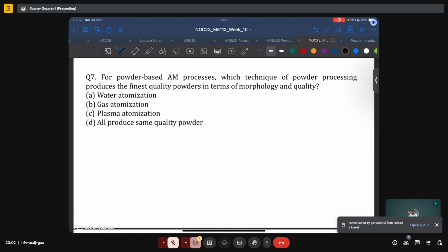Typically, the metal feedstock will be melted and then it will be atomized into small particles, which then solidify and form the characteristic powder. This atomization can be done by water, in which case the produced particles are typically of irregular shape, not always spherical, and so the sphericity is poor.